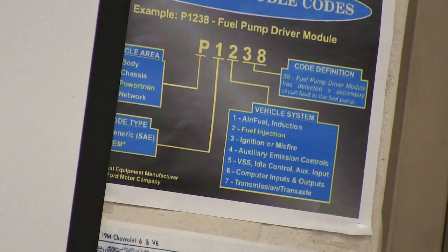And I will tell you something else too, a mass airflow sensor can keep one from starting. In some cases, it doesn't usually happen, but I have gone out there and found vehicles on the lot that wouldn't start, and you go and plug the mass airflow sensor and they fire right up. And so,